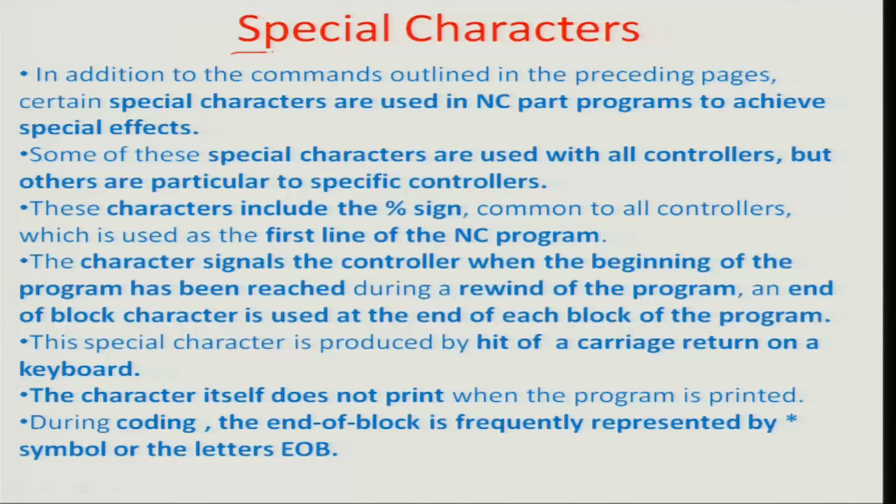So that's sort of bringing us to the end of this particular module when we are talking about the various programs. The only other small thing which we need to mention are sometimes special characters like the percentage sign, etc., which are used to just indicate the start of the program or the stop of the program. So generally the percentage sign common to all controllers is used for indicating the first line of the program. And so these special characters are just over and above whatever has been discussed so far in terms of the G commands, the F and S, the axis motion commands, the identification commands, and the miscellaneous commands. So they are also serving some role, the special characters, in terms of start of program and stop of program.